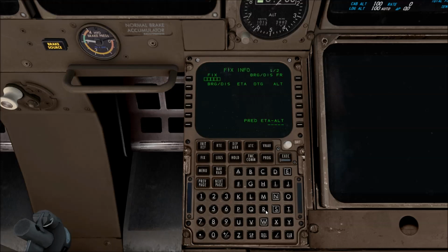Finally, we'll go to the fix page, enter, for example, the MSA based on London VOR. So we'll pick up the first London waypoint here, set 25 DME /25 or circle 25 DME on London, and then the transition altitude, for example, here in the predicted altitude. And in the VNAV climb page, we'll set also 6,000 feet for the transition altitude around London. And that's pretty much it. At this stage, we'll go back to the INIT REF button and PERF INIT page and wait.